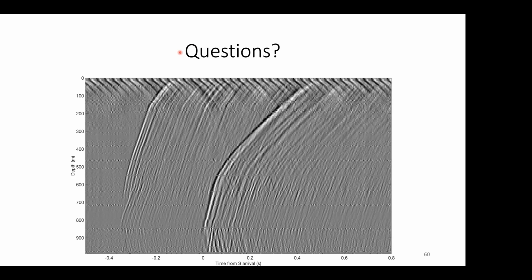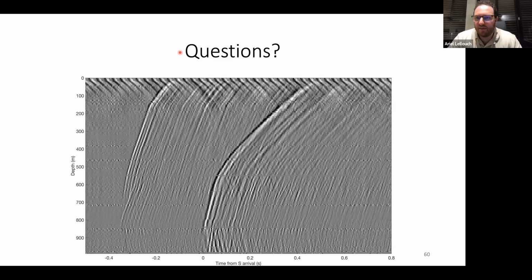Yeah, I think eventually it's beamforming, because I'm trying different angles of incidence and just trying to see if the energy is coherent. I think it ends up being the same way. Honestly, I did not experiment with downsampling the array. I just used the full resolution because computationally it was not the end of the world. Also, I did not use the beamforming formulation directly. I just think it ends up being the same principle of a plane wave hitting your array.